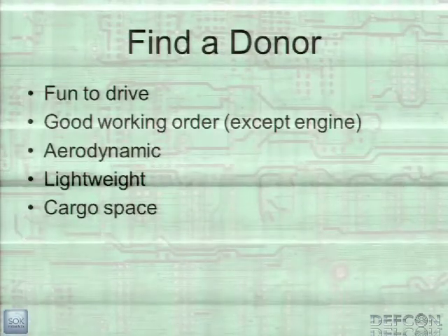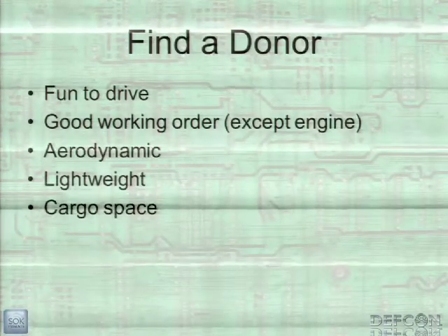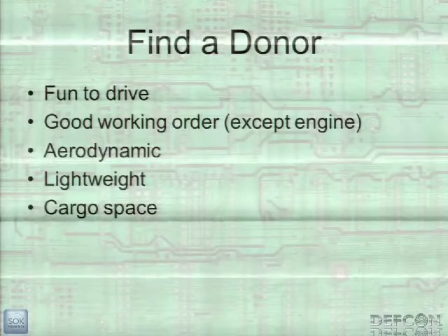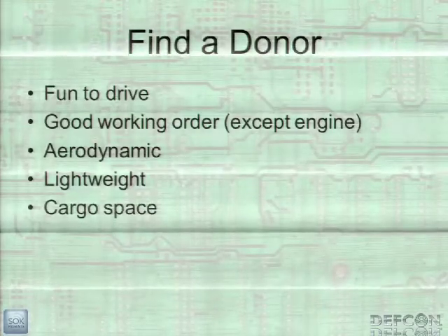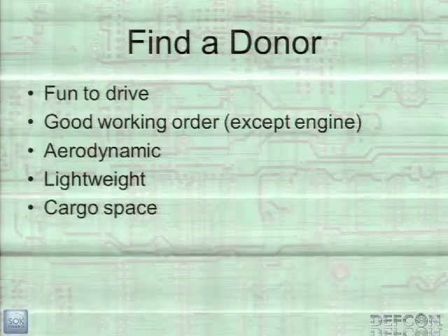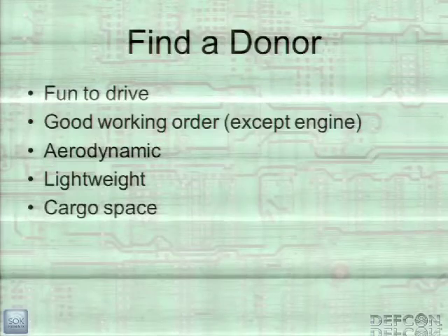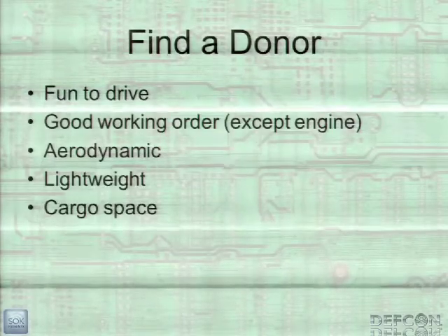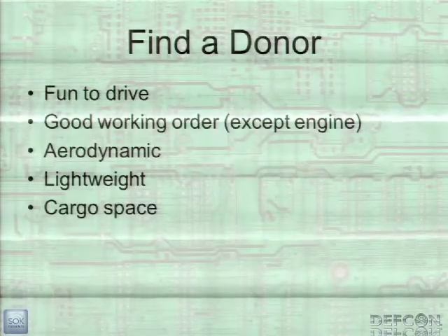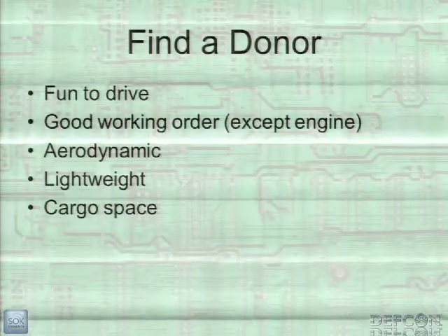So make sure it's in good working order. You don't want some rust bucket that's going to fall apart in a few years. Your EV components should last decades, so you want to make sure that the car is pretty good too. Aerodynamic, depending on what you're doing, if you're doing long distance, high mileage, you're going to want an aerodynamic car. For short range, low speed, something like a VW Bug is fine because it doesn't matter if you're a brick. It doesn't even matter until you get over 30 miles an hour and it's still not even much at 45.